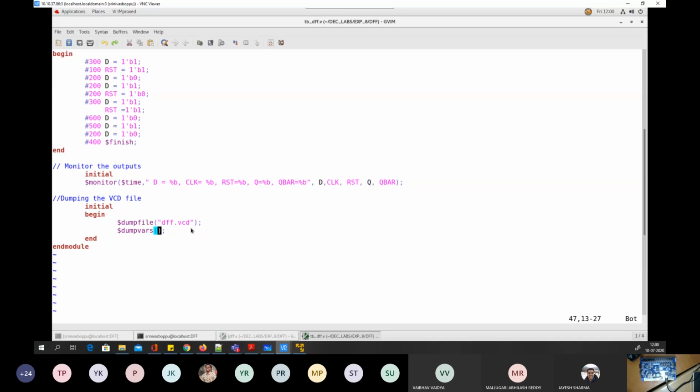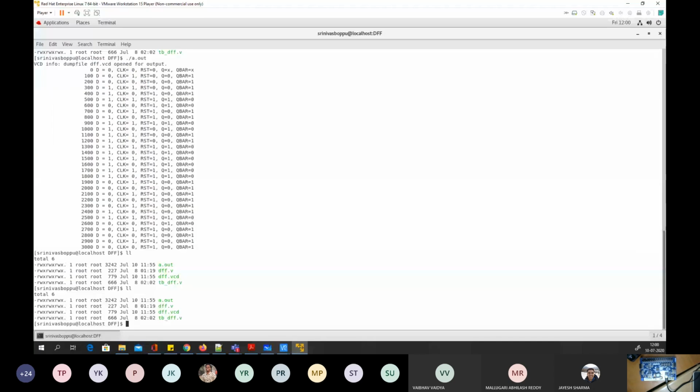For instance in this case, we don't want to see q and q bar, but we do not know whether the logic is correct or not. If you know there's no need to watch q bar, you just neglect it here. Okay, now since we are done with that, as I said, we will generate this file a.vout, and then what we need to do is execute this file.